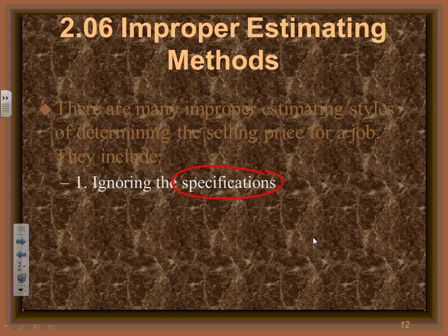Does that make sense? And when you build a lot of stadiums, you develop an idea that every time you have an air handling unit, you have to have a disconnect, and this one does not have a disconnect. Well, maybe it's provided by the manufacturer. So you start asking certain questions so you know that the other disciplines are not expecting you to do certain things that you are not aware of. Does that make sense? Check the specifications, not just the electrical, not the 2600, but also mechanical and other specifications.